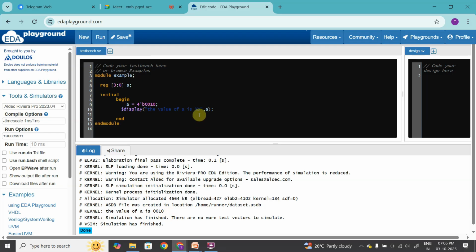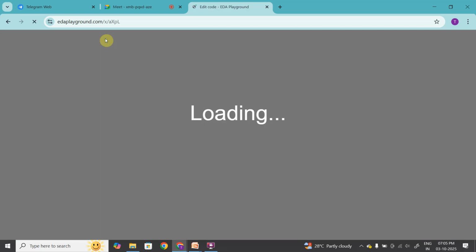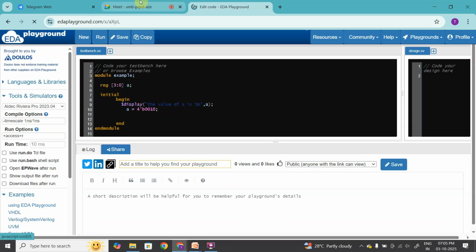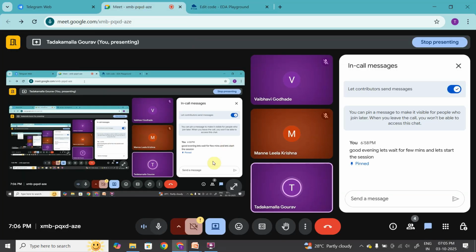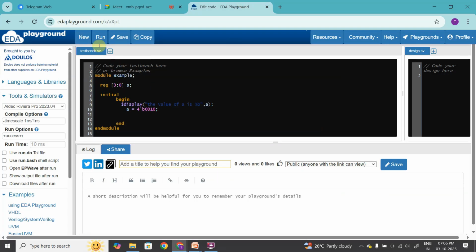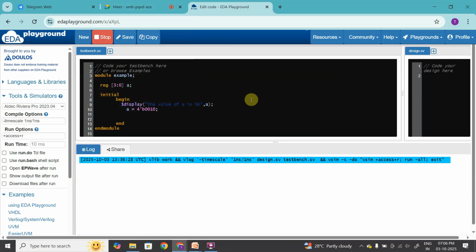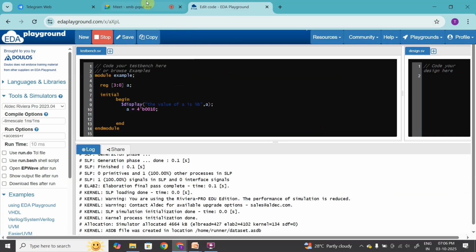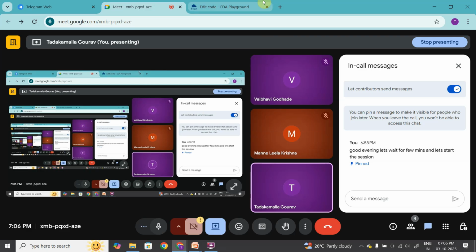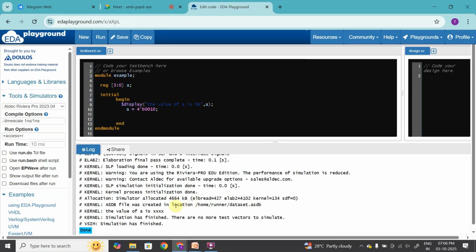Now what I am doing is using this display function before the assignment. That means I am using it here. Now what will be printed? Take your time and let me know. Will 0010 be printed in the console if I'm using $display above my assignment? Let me show you what is getting printed. I'm getting all unknowns.